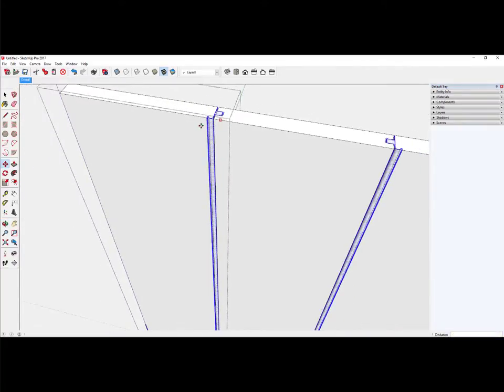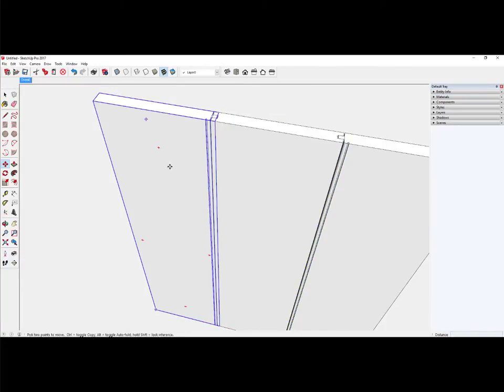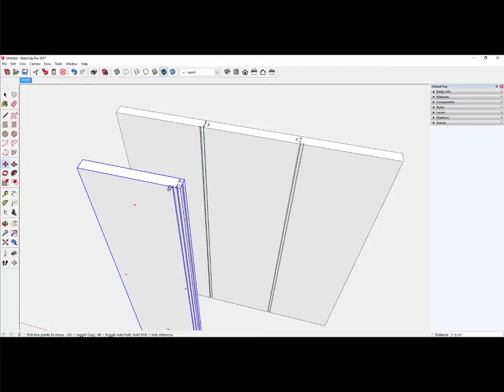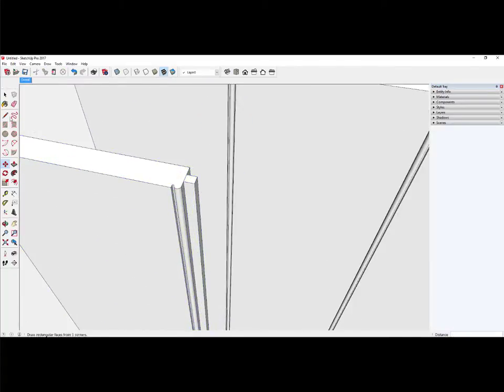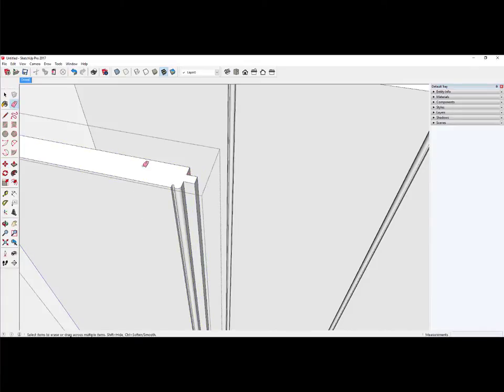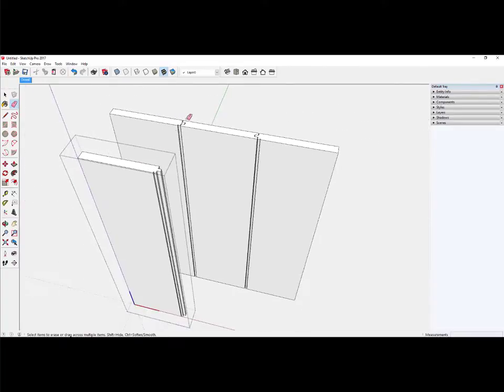So now I've lessened the width of the end slat, and I've got a 16th at each joint now of airspace for movement. Now let's go back to some of the cleanup here. I brought a copy out, and I can see an edge that I can remove. That edge will also be on the bottom face.